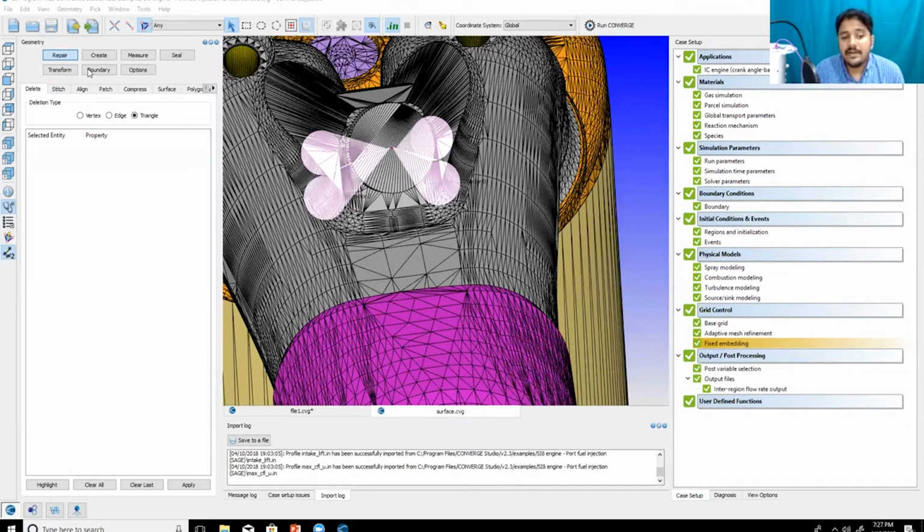What is the parameter of interest if spray is here for grid dependence, as you mentioned? Well, what I would do is I would look at something like liquid penetration length or vapor penetration length. So the idea is quite simple. Are you familiar with liquid penetration length, Nitin? If not, just let me know. I can draw a quick chart and explain.